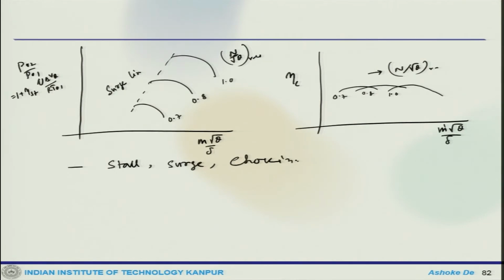So, in compressor choking, flow does not necessarily reach the sonic velocity. So, keep that in mind. This is a different condition compared to compressible flow when we talk about the typical convergent divergent nozzle, where flow choking means it reaches the sonic condition, but in a compressor that does not necessarily mean it reaches sonic velocity.